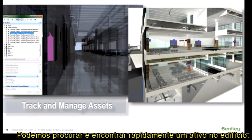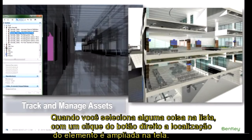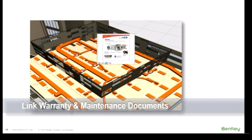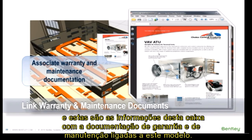We could be tracking and quickly finding the assets in the building. We have several different ways with the item browser and the Data Group Explorer. Once you highlight something on the list, you right click and it zooms right in to find it for you. So we could also be linking warranty and maintenance documents to objects. In this case, we've linked the VAV box information to the actual VAV box. So it's all that warranty and maintenance documentation is linked in the model.